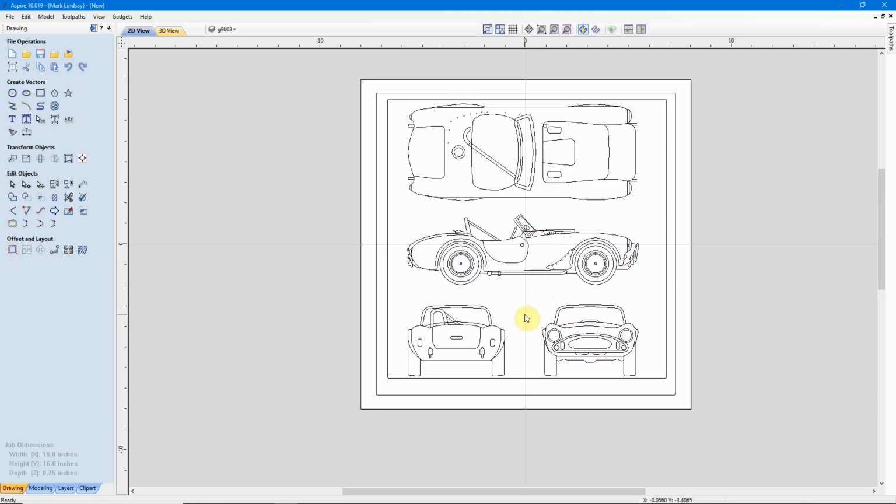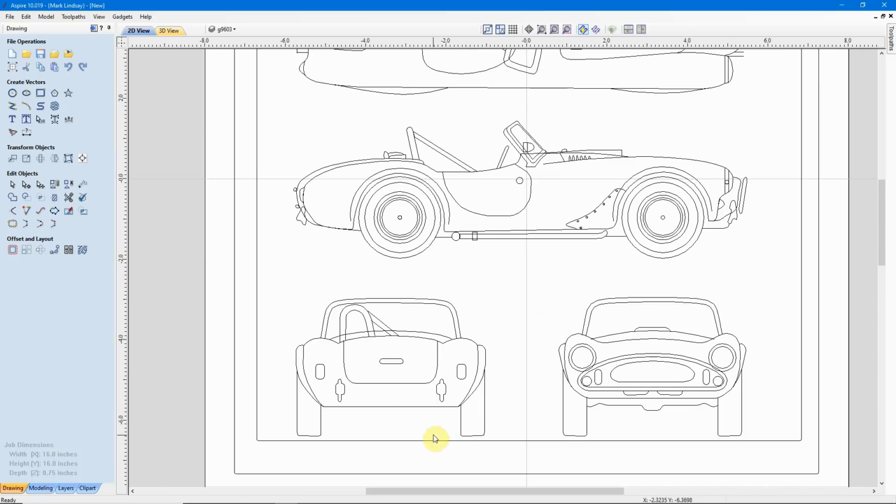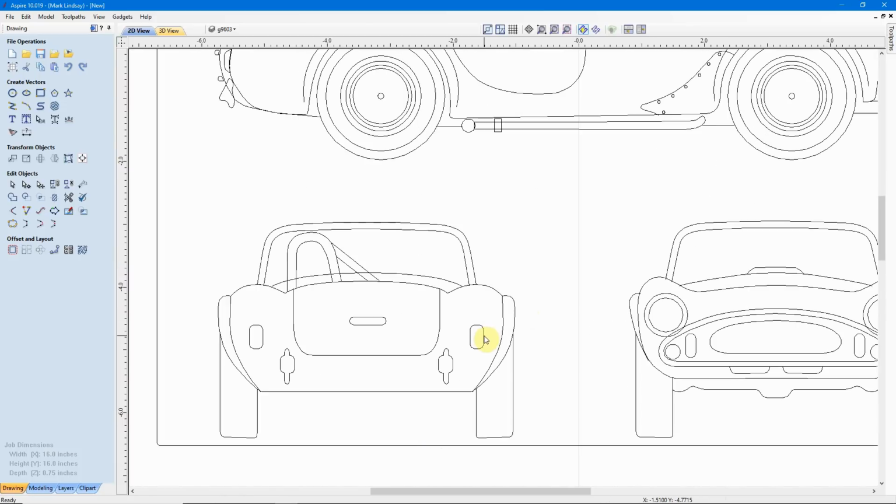And there is a subtle but profound difference between VCarving and engraving. Remember, VCarving carves inside the vectors. It carves in between the vectors here. And in this case, you do need a closed vector. So these lights here would VCarve. The little light and license plate mount on the trunk would VCarve. This sculpture line here would not.